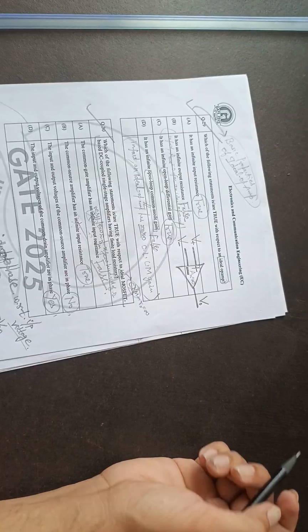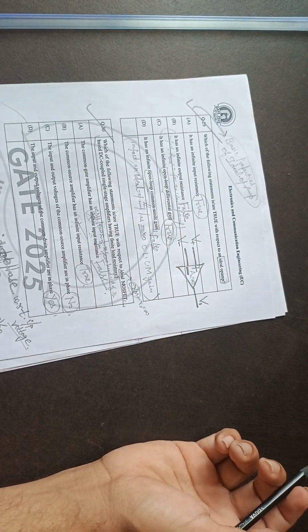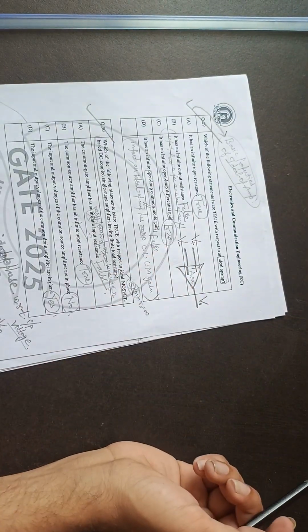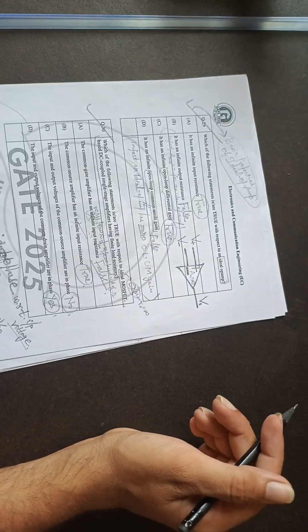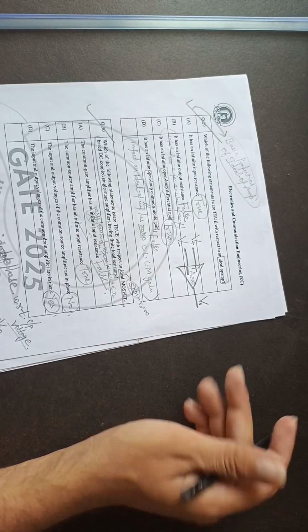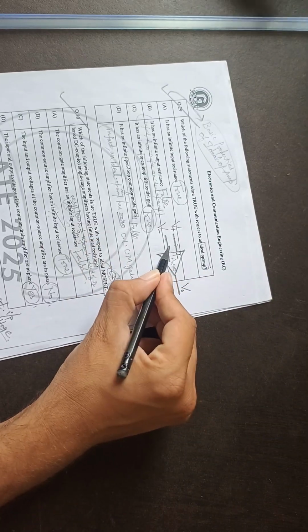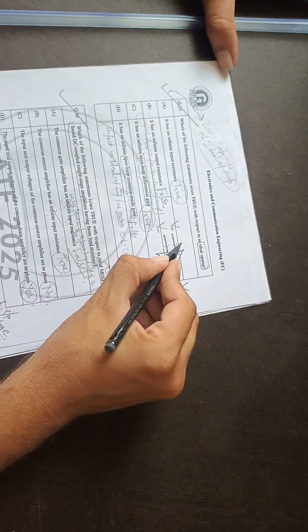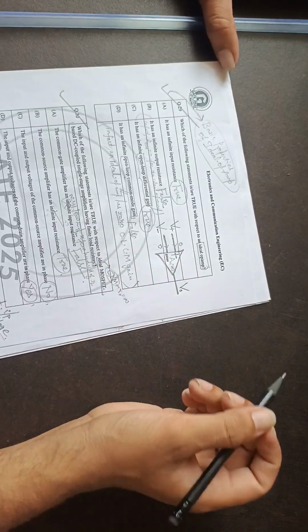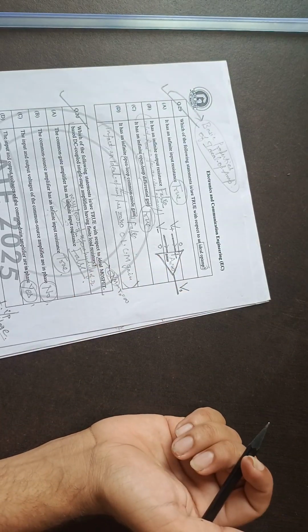The third and fourth questions are theory based questions. It is about an ideal op amp. Ideal op amp has infinite input resistance. It is true because when we assume the op amp is ideal, we assume that no current enters into the input ports, plus and minus, so both currents are zero because we assume it has infinite input resistance.